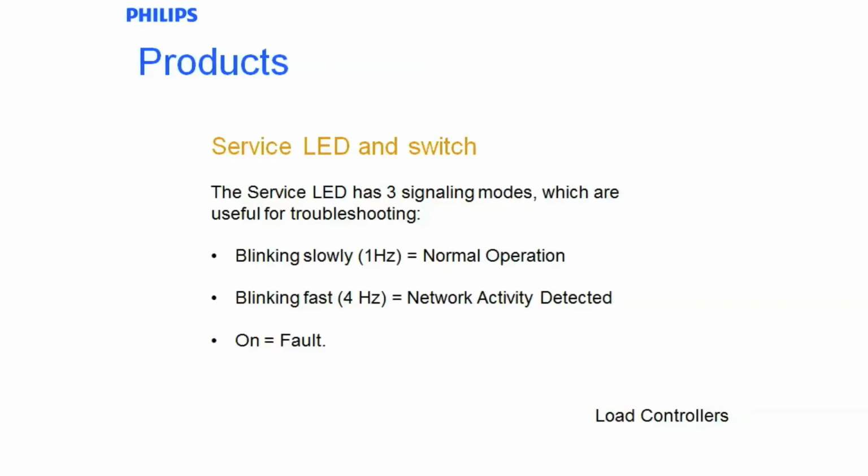If we do 1 push, the device transmits its network ID. By default, it will transmit its device code and its box number out onto our software applications. When we do this with most of our software applications, the device will then get polled for its serial number, and that's typically how we start commissioning some of our devices.